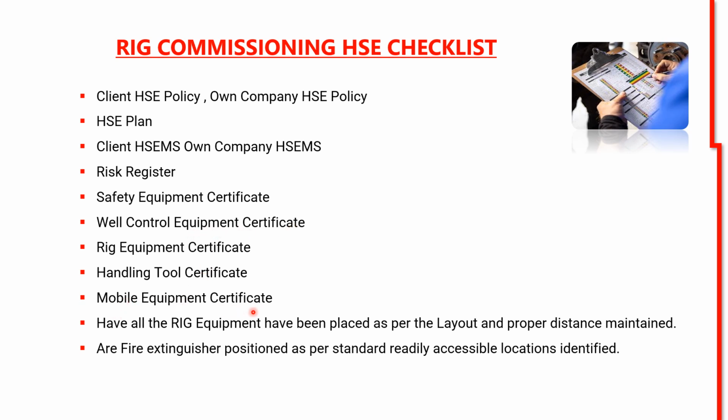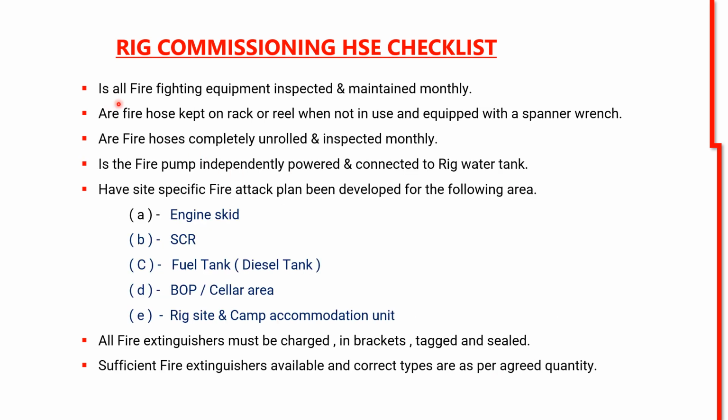Mobile equipment certificate. Have all the rig equipment been placed as per the layout and proper distance maintained? Are fire extinguishers positioned as per standard, with readily accessible locations identified? Is all firefighting equipment inspected and maintained monthly?